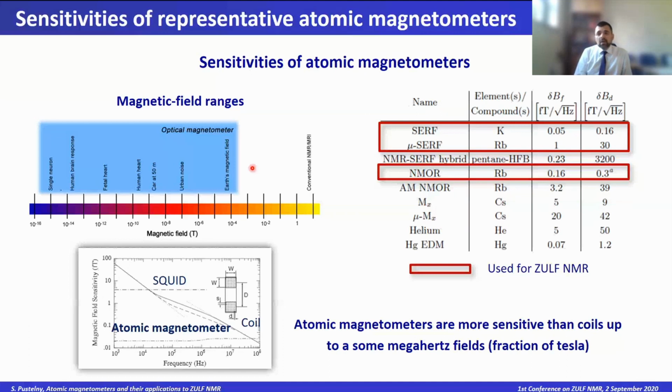As you see, these are typically an order or maybe even 2 orders of magnitude worse in different scenarios. But one important and positive piece of information is that the sensitivity of the system is on the order of some tenths of femtotesla, because we have systems that are extremely sensitive, and you can achieve a sensitivity of 10 to minus 15 Tesla per root hertz in our system.